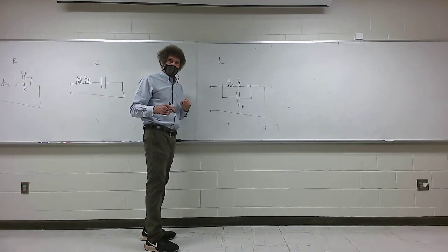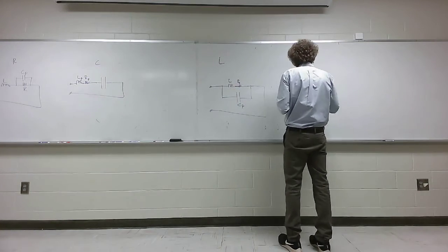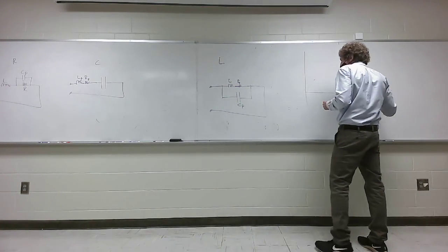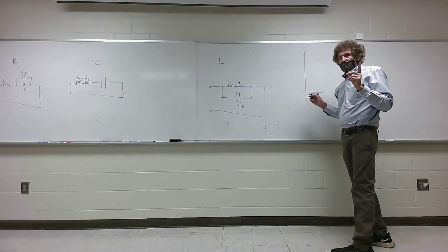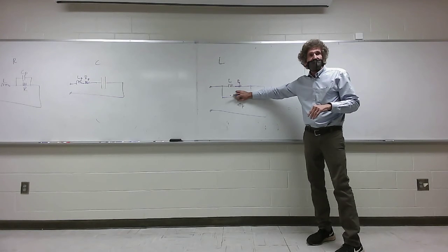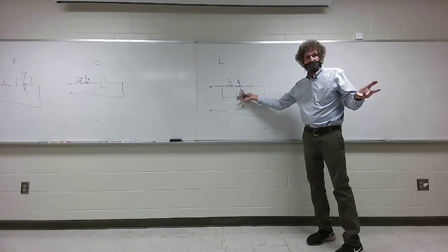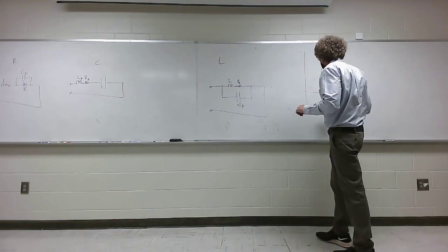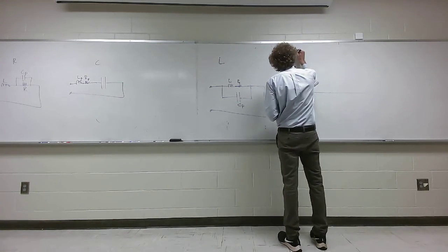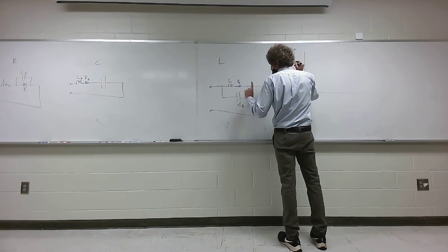Now this one itself, I can develop the model, but this is how inductor models almost always look. At very low frequencies, this capacitor is an open circuit. But instead of having 0 resistance, because there's a DC resistance to that wire, there will be some finite but very low resistance. So if you looked at this, and this would be 20 times the log of the actual impedance of that inductor